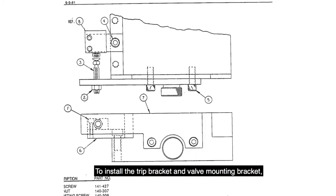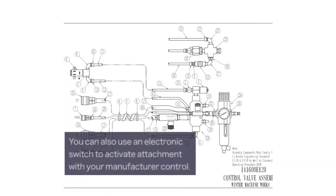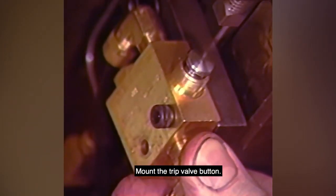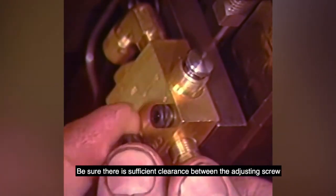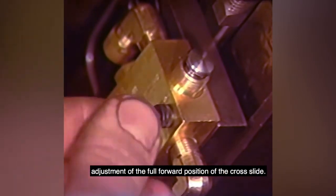To install the trip bracket and valve mounting bracket, refer to the trip valve assembly drawing. The trip bracket must be mounted in a way that it can depress the trip valve button when the cross slide reaches the full forward position. Next, advance the slide to the full forward position and assemble the adjusting screw and jam nut into the trip bracket. Mount the trip valve button. Be sure there is sufficient clearance between the adjusting screw and the trip valve button. The adjusting screw must not interfere with the adjustment of the full forward position of the cross slide.